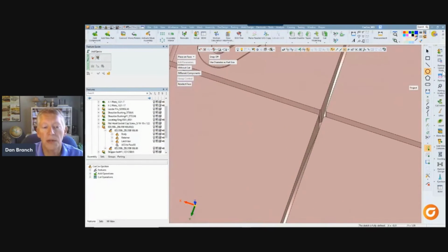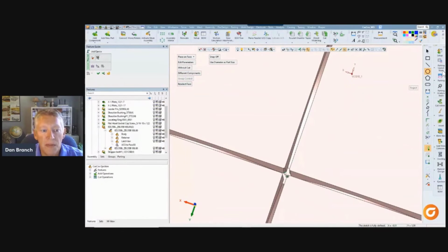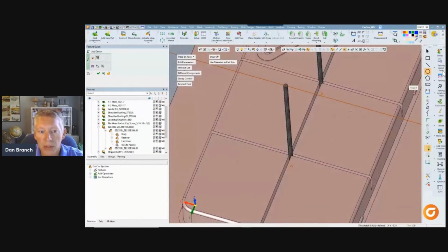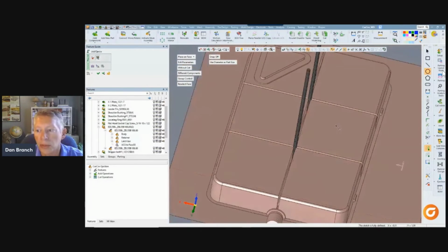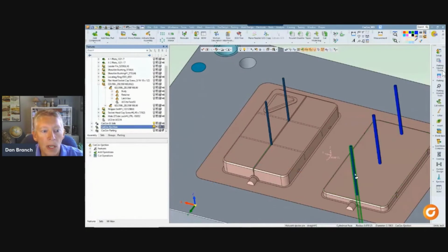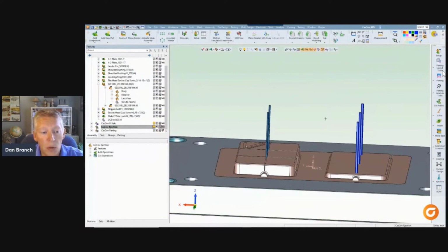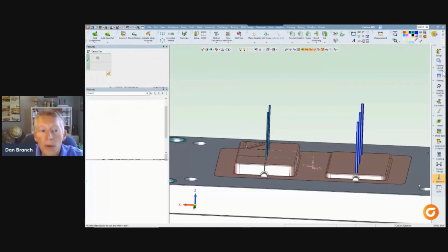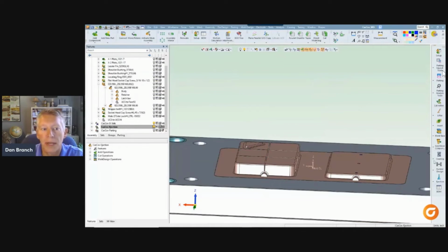Now, whenever possible, Cimatron uses automation to place well-known types of mold components. So I don't have to specify the plate an ejector pin sits on because a smart rule handles that. I don't have to specify the pin length. The system can calculate that too. All I really have to do is select the pin locations. Now, ejector pins are one of the components that get special treatment in Cimatron. Being so common, a couple of dedicated functions exist to help speed up the work. One of these is for trimming the ejectors to match the shape of the part. It's just been completely automated.